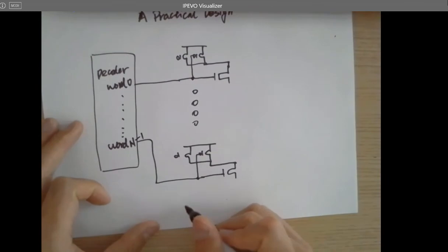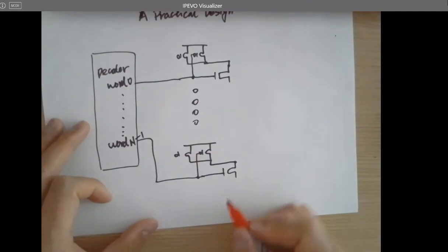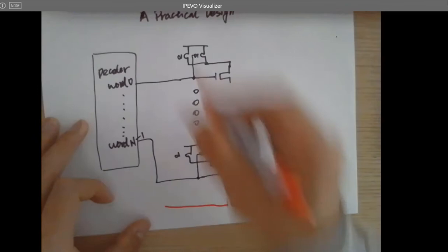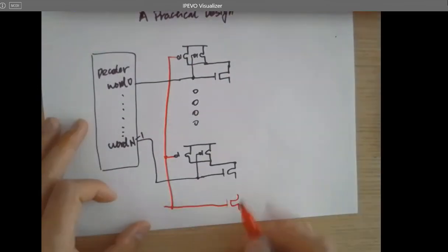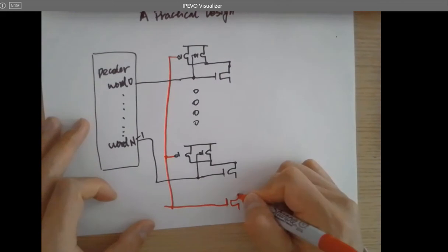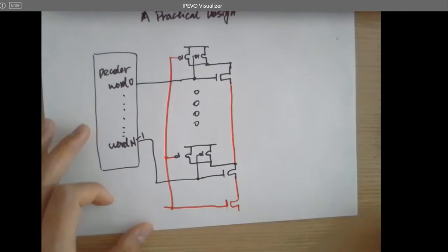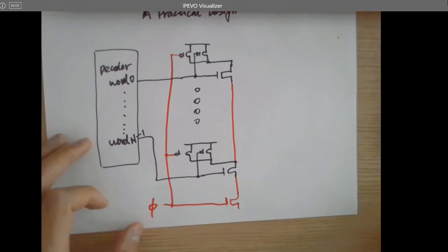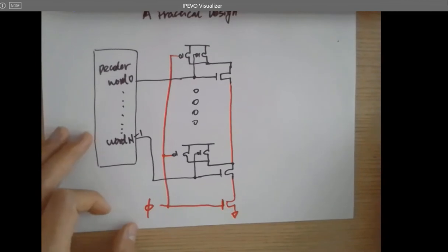It should be controlled by clock, which is eventually, after you have all the cells together, you just have a final NMOS at the bottom. And you'll short all these PMOSes to this one, and then to this NMOS. And this will be shorted to this line. And these are being connected together as well. Okay, if you do not give a rising edge, nothing will be enabled. Is that correct?